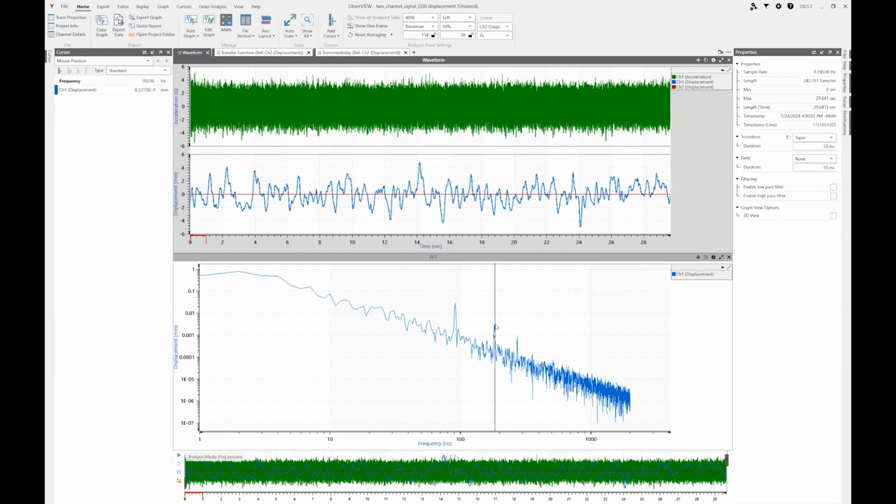That's kind of what we would have expected from what I showed you earlier in the equations, is that we doubled the frequency. So we had a resonance at 90 hertz, we doubled it, went out to 180 hertz, and we see that we have about a 96.7, might call it 97% reduction in the amplitude. So the factor of 2 rule, if I follow that as a guideline, does a lot to mitigate the risks of failures due to resonance.